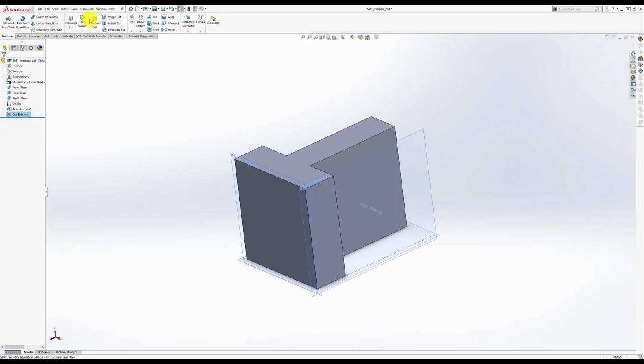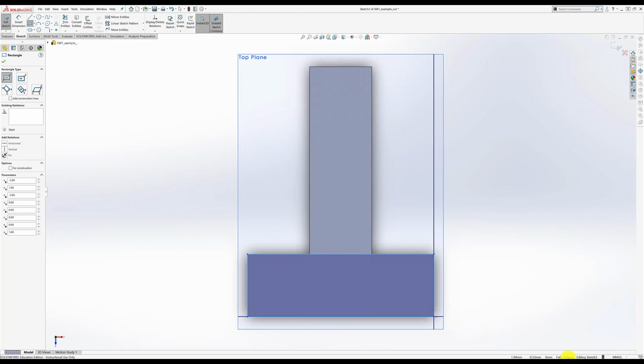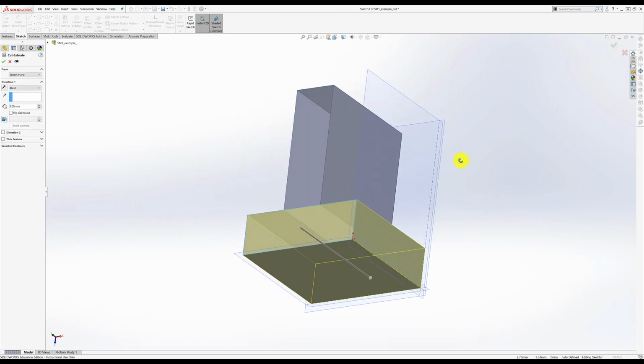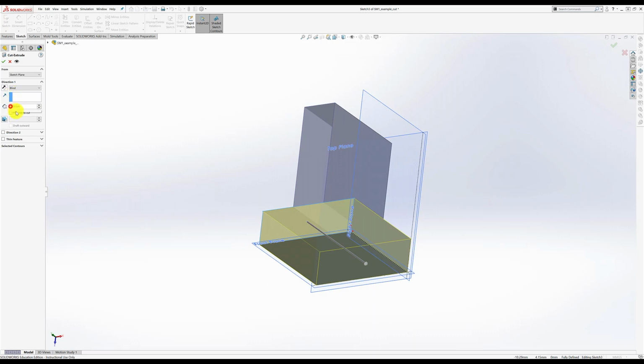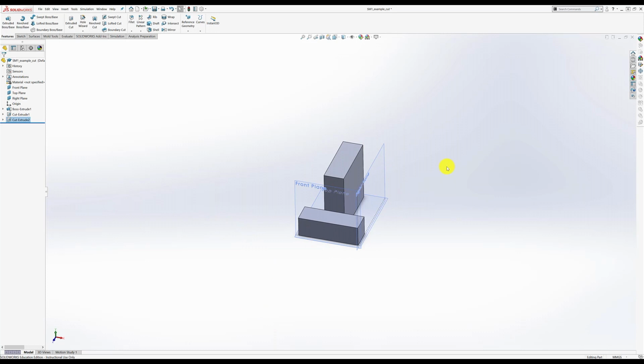All right, so now we're just going to make some more cuts until we end up with this shape. So I will, at this point, make it coincident with that point and coincident with this point, and I should be fully defined, which I am. Okay, in this case, I do not want to go through everything. I instead want to go down just 2 units so that I'm left with a 1 unit high piece right there. Okay, excellent. We're getting closer.